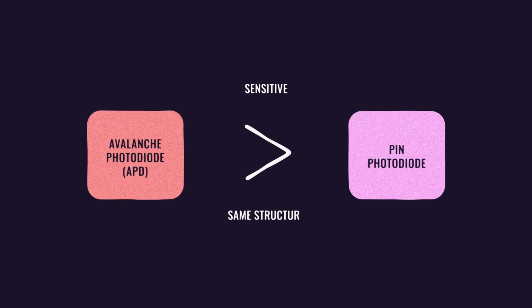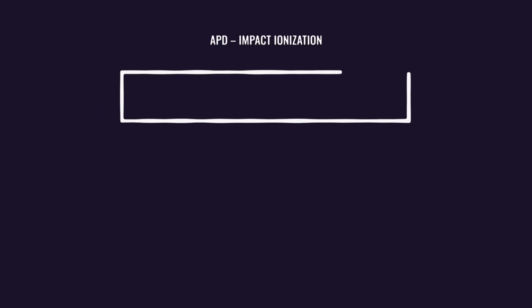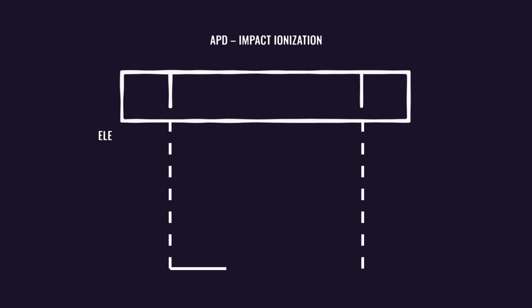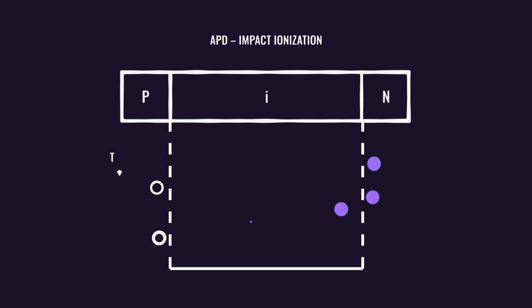The structure of an APD can be the same as PIN diode, but APD has internal gain due to the avalanche process. By adjusting the applied voltage, the electrons and holes in a relatively high electric field will gain enough energy to impact ionize with lattice atoms. This ionization produces secondary carriers, leading to a chain reaction, generating more electrical charges and amplifying the photocurrent.